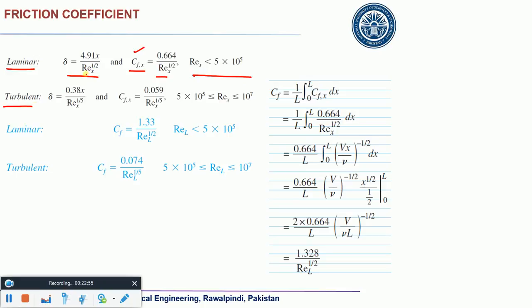For turbulent flows, you cannot solve, by the way, those relations came from the analytical solutions. You remember those Blasius profiles I talked about? Although I didn't solve the Blasius equation, I just gave you the similarity solution, and from those similarity solutions you came out with those expressions. You cannot solve those Navier-Stokes equations for turbulent flow. So in any case, you have to go to the experiments, or you have to perform the numerical simulations, right? So these relationships are experimentally measured relationships.